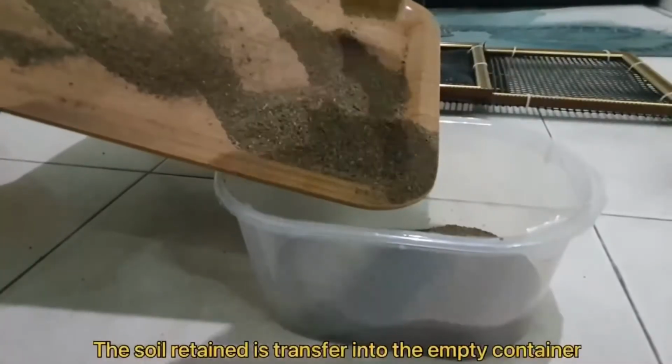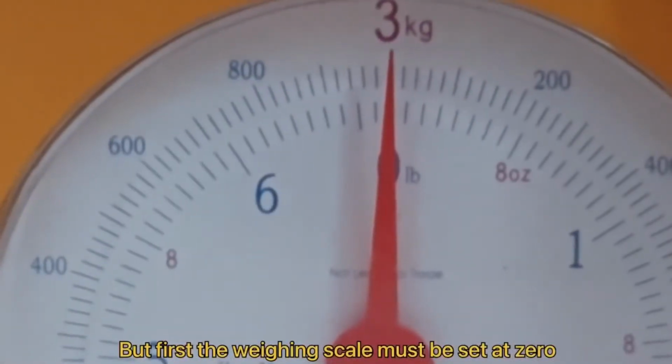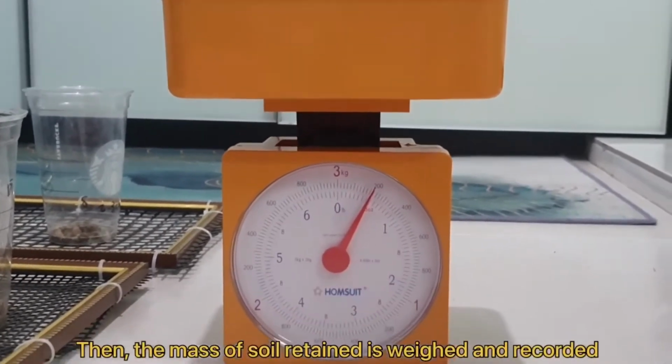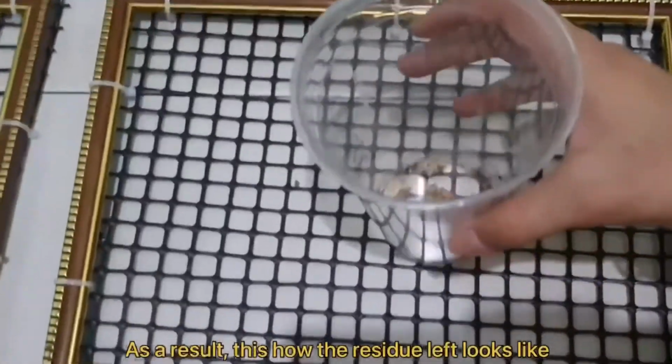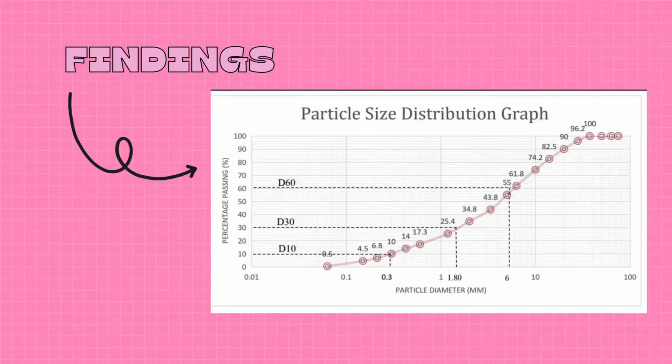The soil retained is transferred into the empty container, but first the weighing scale must be set at 0 to avoid any error in reading. Then the mass of the soil retained is weighed and recorded. As a result, this is how the residue left looks like after the dry sieve test. This is the grading curve that has been obtained from the expected result in this test.